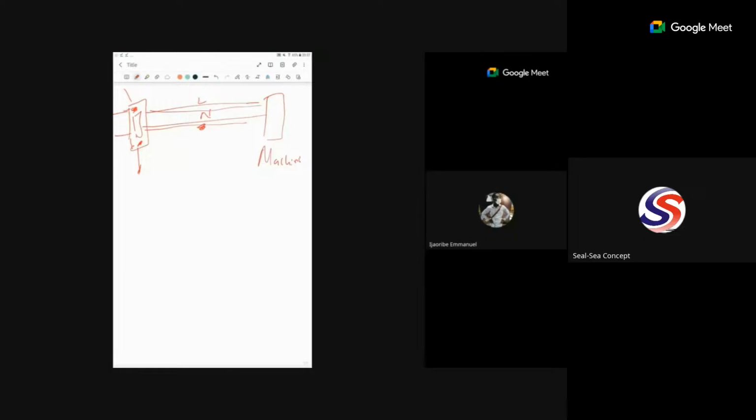So in a case like that, you want to test for what? Continuity. Maybe the conductor has actually cut inside. So you may have to open the wire around here. You open the wire around here. You first test from point A to point B here. You put your probe.